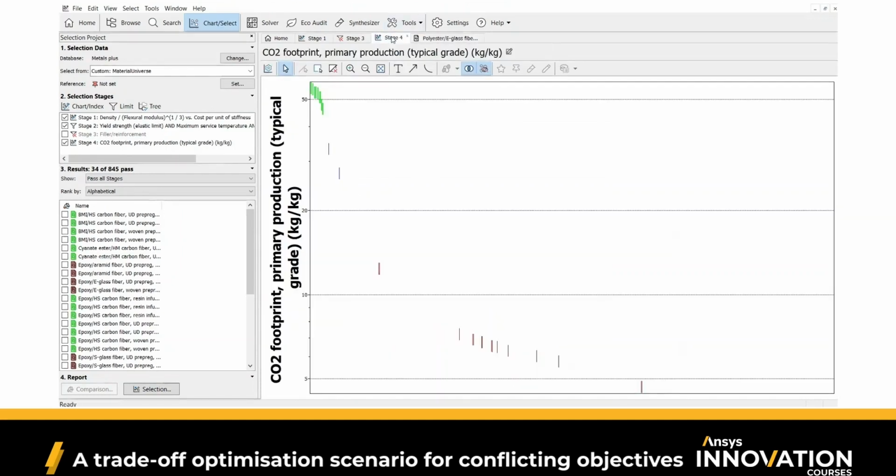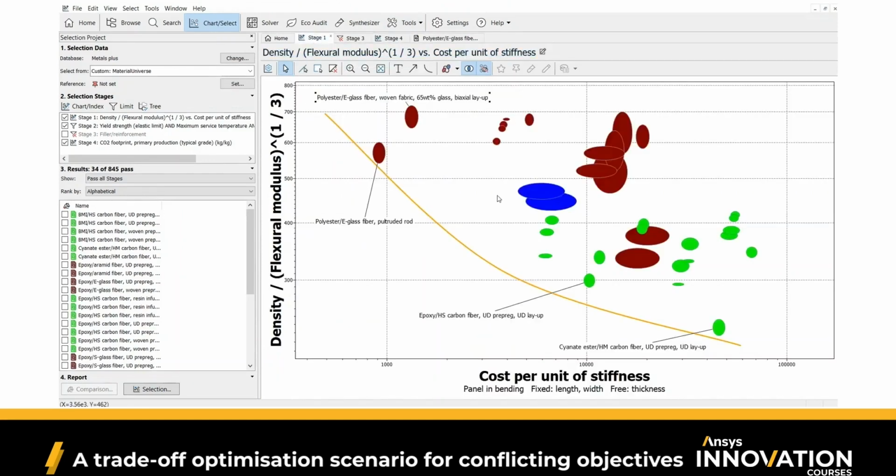So it is not a far off choice that we have come up with, but again, the discussion that can take place after going through this systematic material selection methodology depends on the prioritization of whether lightweighting is more important to us, or cost performance, or the environmental impact of these materials, or a combination of these. Okay, so that's the material selection step of this course for the monocoque chassis. Let's move on to the next stage.